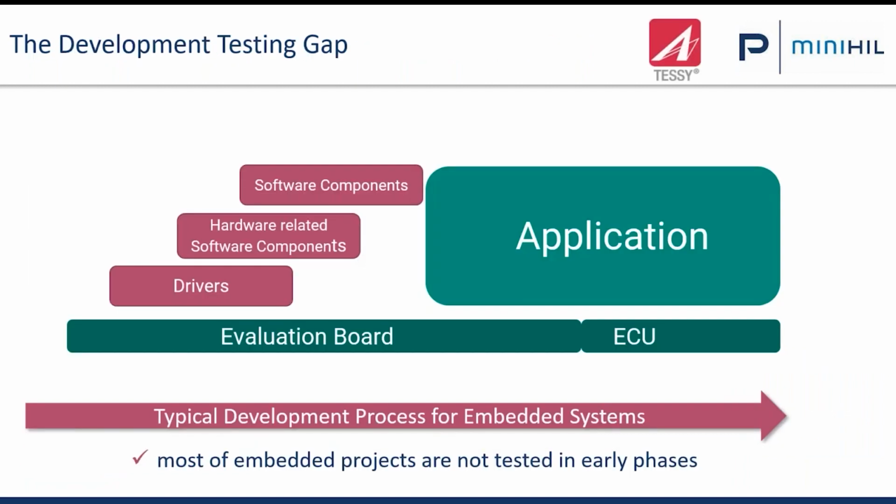So let's have a look at the development process. Usually you start to develop your embedded software on an evaluation board. On the right microcontroller, you program or configure drivers. You program hardware-related software components, such as a motor controller or a battery controller or bus protocols.